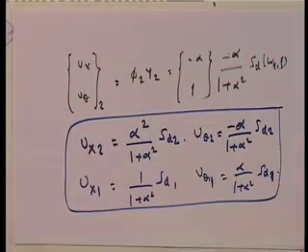So, this in essence is what in a multi-storied building you have, rotations despite there being only a translational excitation, because there is lateral torsional coupling, and because of that coupling you have these kind of terms. And I have actually given an example problem to show you how to go about it.